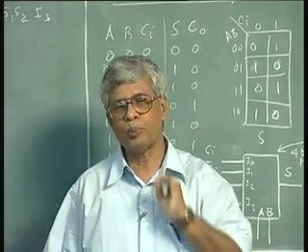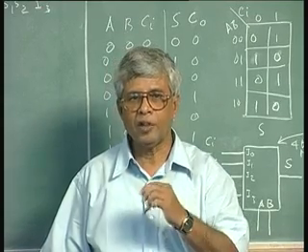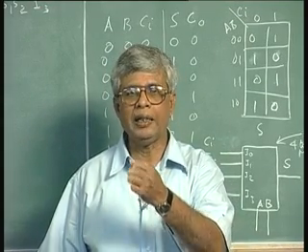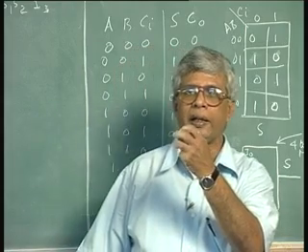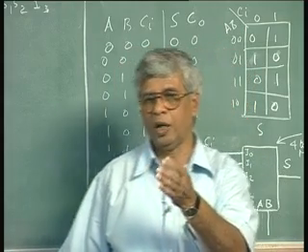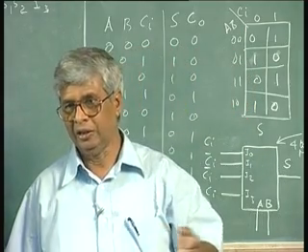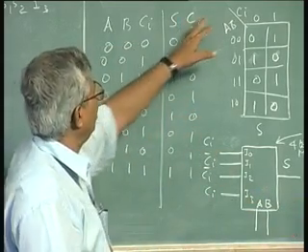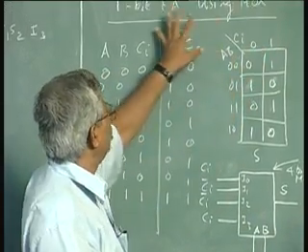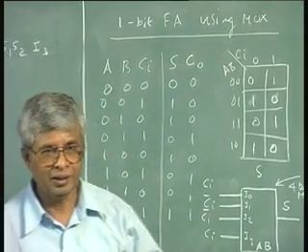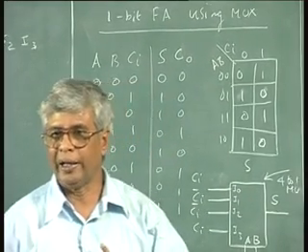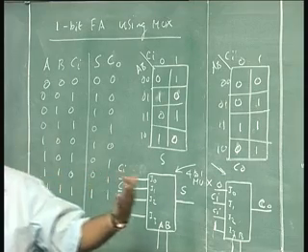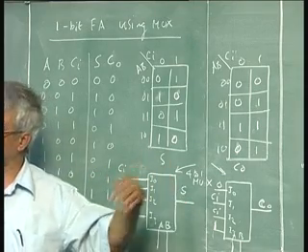The design becomes simpler, but a sort of extra effort is required. It is an effort in terms of properly identifying the requirements of the chip. For example, even if I did not tell you to use a mux, if you are asked to use an MSI and get a 1 bit full adder, you should know how to do it, because there are other ICs also we can use. I can get a decoder using other ICs also.